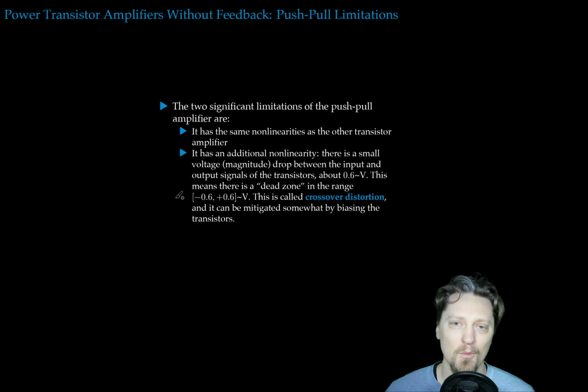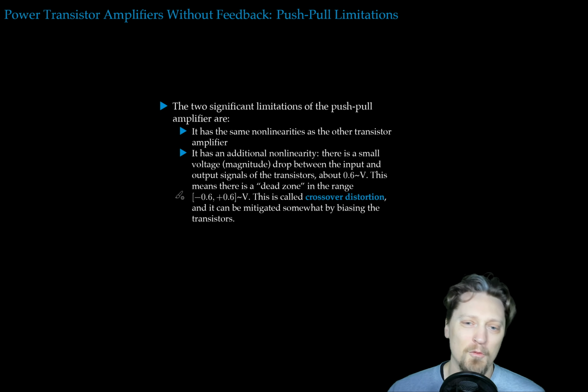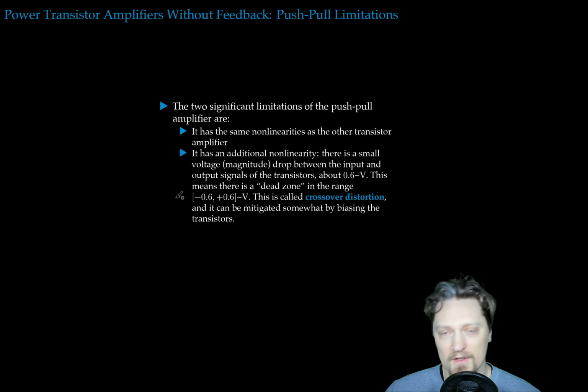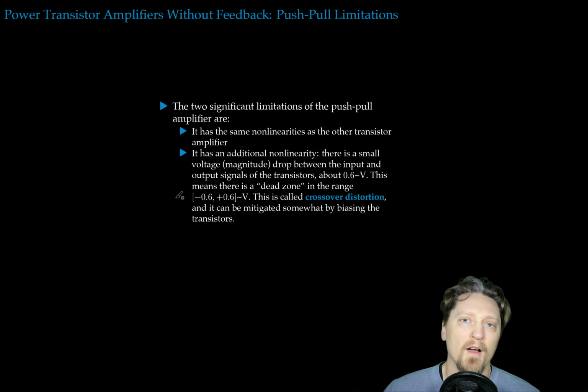Unfortunately, it's at the worst spot. We would like to do a lot of things near 0 volts, and there's a dead zone in our amplifier there. This is one of the most significant limitations of the push-pull amplifier.